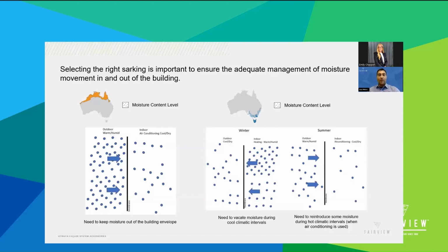One of the first things to know when selecting the best Rainscreen system is knowing the factors that include climate conditions, building height, wall assembly type, and the cladding materials used for your project. For instance, if you look at the overall Australian territory, in regions with high humidity or frequent rainfall, an exterior cladding application might be optimal for managing moisture behind absorptive materials and preventing moisture from entering the building. For a project focused on maximizing thermal efficiency with continuous insulation, for example, exterior framing options can provide reduced moisture management while minimizing thermal bridging in so-called breathable walls.